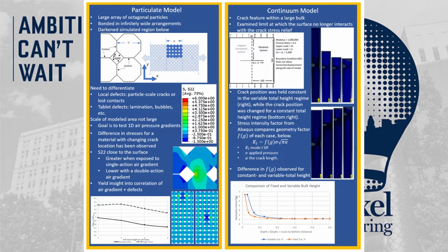We also developed a continuum model in ABAQUS using a crack engineering feature instituted within a bulk solid. Using the stress intensity factor evaluated about the crack tip, the stress concentration was examined, and we can obtain a geometry factor for this system.